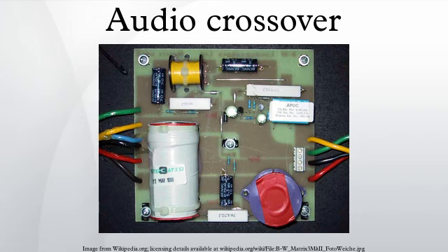Audio crossovers are a class of electronic filter used in audio applications. Most individual loudspeaker drivers are incapable of covering the entire audio spectrum from low frequencies to high frequencies with acceptable relative volume and absence of distortion, so most hi-fi speaker systems use a combination of multiple loudspeaker drivers, each catering to a different frequency band.